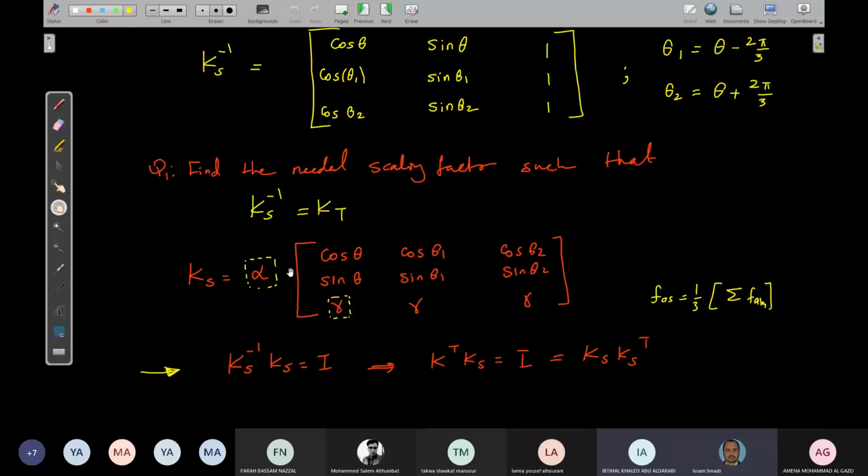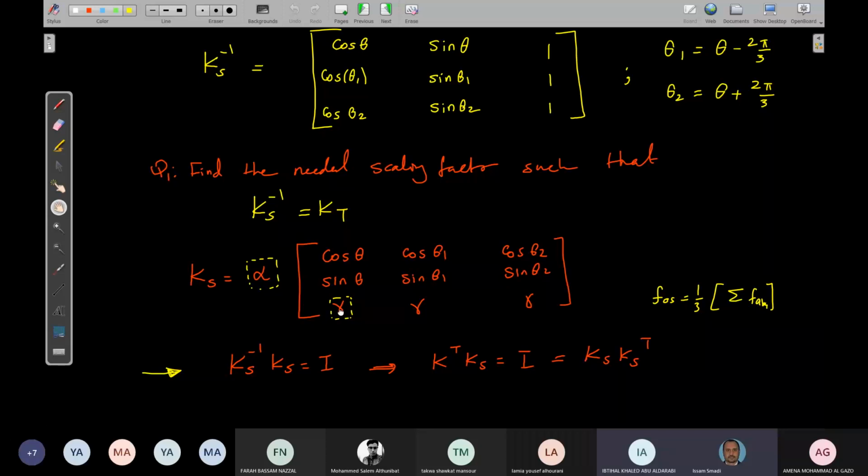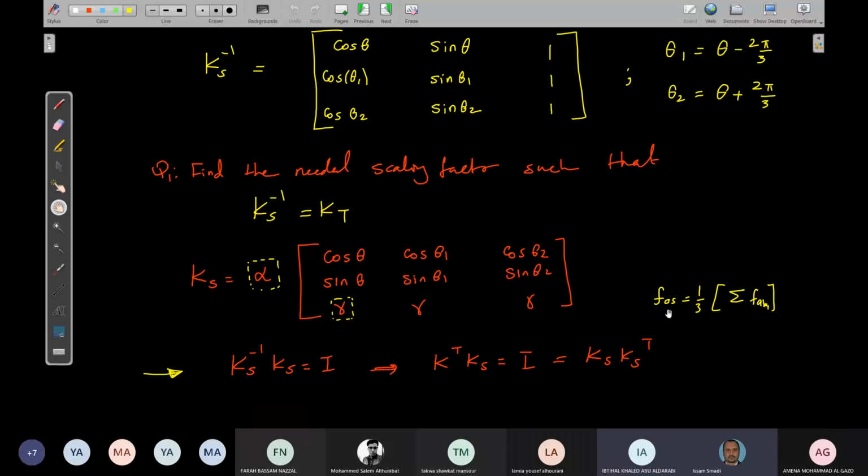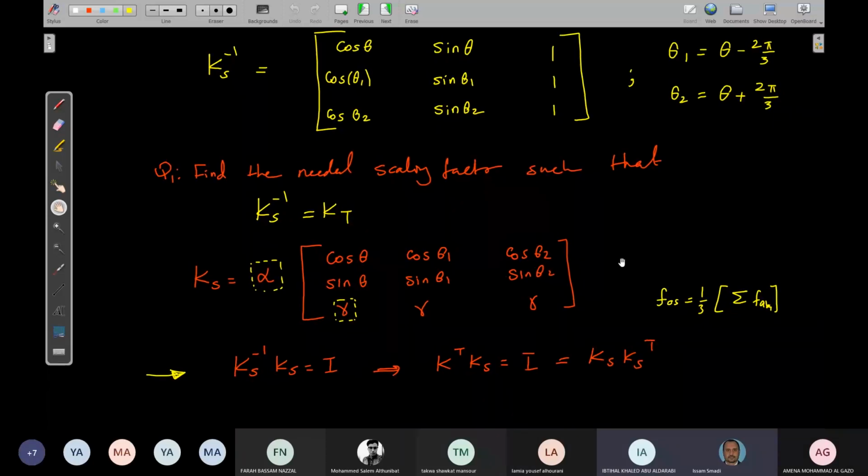So if this is the case, I need to change the scaling factor. If I change the 2/3, for sure I should change the 1/2. Why? Because in the end of the day, I need to maintain the zero sequence, which has no relation with the transformation. The zero sequence is only proposed in order to complete the square matrix.